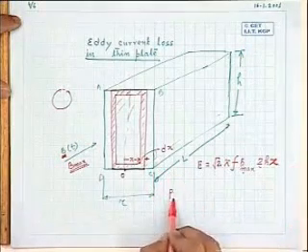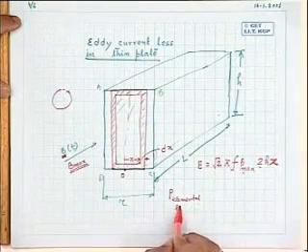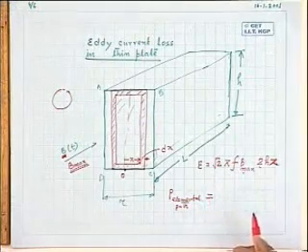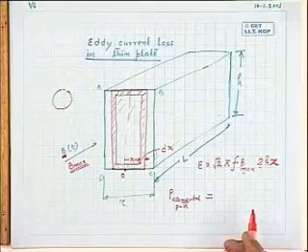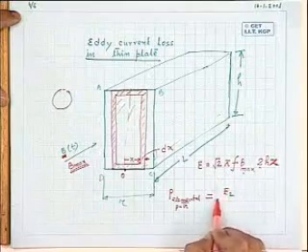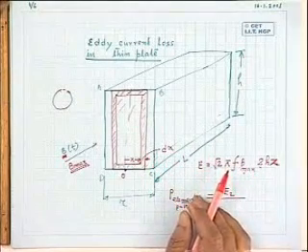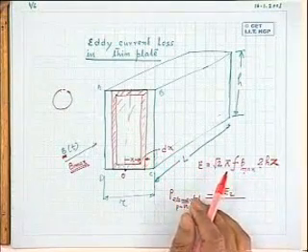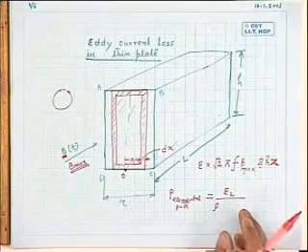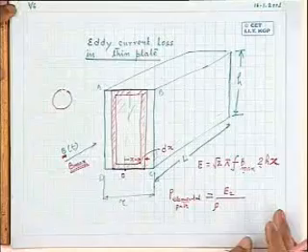The elemental power loss in that elemental path is very simple calculation, nothing great. It will be E squared divided by R, if you assume the path is fully resistive, that is, E squared divided by the resistance of the path. Now let me hear from you, what should I write for the resistance of the path? That is, rho L by A is the resistance of the path.